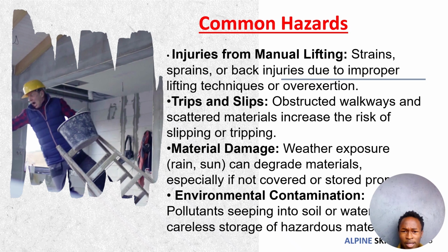So when storing sand, you should ensure you lay out a polythene paper over the area, and then you can place the sand on the polythene paper. Or if it's a cemented floor, you can place the sand there, because you can collect all the sand particles even after construction, and the place can be washed and reused.